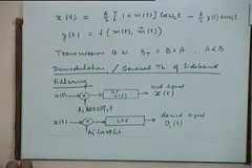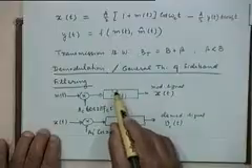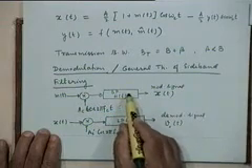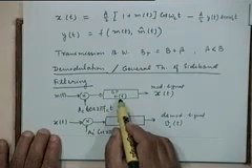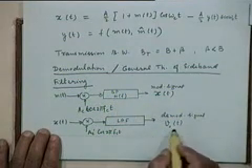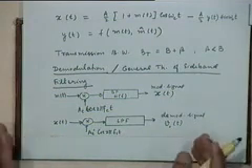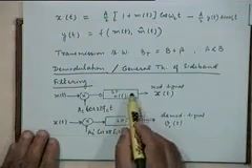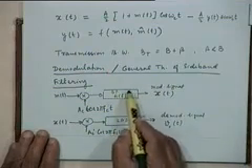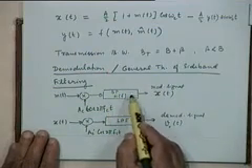The general theory that we are going to discuss addresses the following questions. What kind of band pass filter, or high pass or low pass filter, should I use at the transmitter, what kind of H(f) should I select so that v_o(t) is proportional to m(t)? Because we are suggesting some rather complicated filtering here in the VSB case.